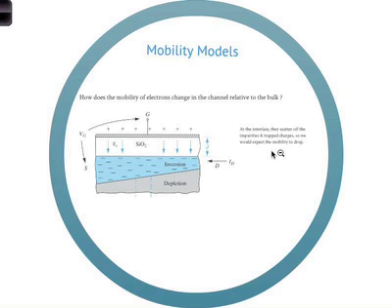So essentially it says at the interface, the carriers, the electrons, the holes, they scatter off the impurities and trapped charges. And we'll introduce this in a little bit: although we assume that the oxide is essentially a pure insulator, in a real oxide you always have some trapped charges. Okay, there are impurities, which means they're sodium ions or whatever, which can also scatter electrons. They can have Coulombic scattering. So if you have a charged particle and another charged particle moving next to each other, you can have some scattering. Okay, so-called Coulombic scattering, and that would also force the mobility to drop.